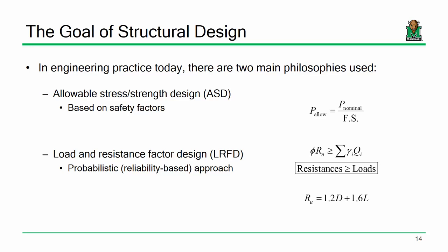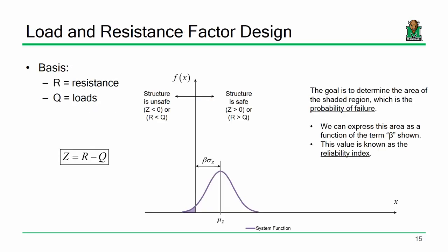We're not talking about geotech, though, in here. We're talking about structural engineering, and a lot of the components are manufactured products, things like bolts, and in concrete design, things like rebar, as well as beams and columns. So we can be a little more scientific and a little more refined. What we end up doing is developing a design philosophy known as load and resistance factor design. It's a fancy way of saying that we apply two different types of safety factors: safety factors to the loads and safety factors to the resistances.